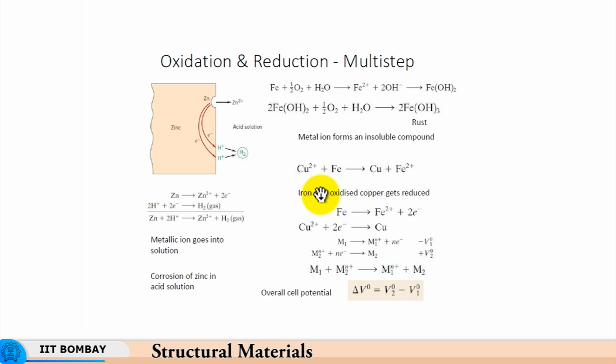Now, in spite of the fact that the zinc piece is an integral piece, how did we get these two different zones? There has to be some reason why this became anodic and this became cathodic. Who decides what makes this anodic and this cathodic? So, what happens at the anode? The zinc goes into solution, the electrons get conducted to the surface here, and then you have hydrogen ions.